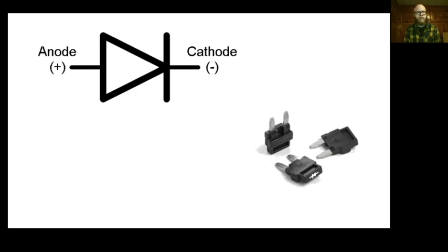So, long story short, the diode points in the direction that current is allowed to flow, and it follows our conventional current flow theory that we're using for everything else in this course and for all of automotive for the foreseeable future. In cars, oftentimes you'll see some of these diodes in the fuse panel. They're often related with circuits like the starting motor and the AC compressor clutch, which is a big electromagnet, and they're there to block the flyback voltage that happens when we turn those components off.